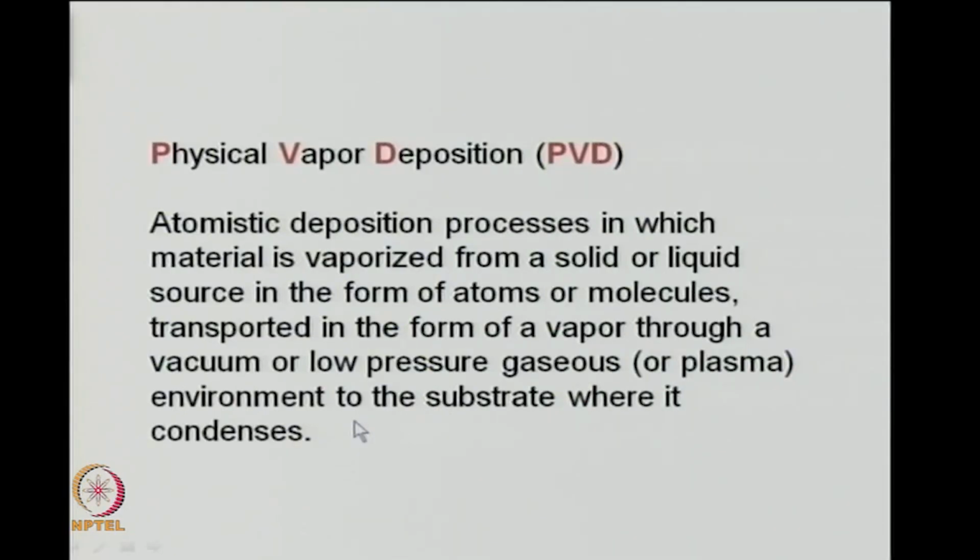The atoms and molecules traveling through this low pressure system are taken towards the substrate, where they condense and form a thin film. So, this is typically a PVD process, which is different from what we studied earlier, the chemical vapor deposition technique.